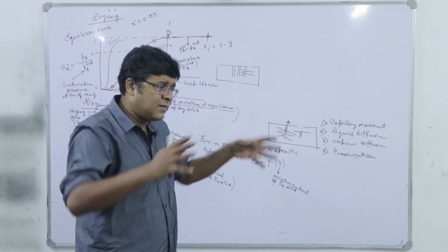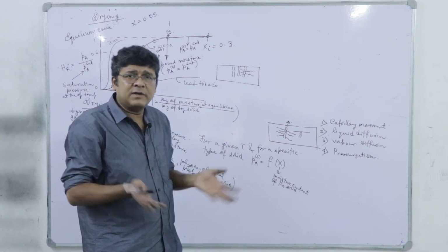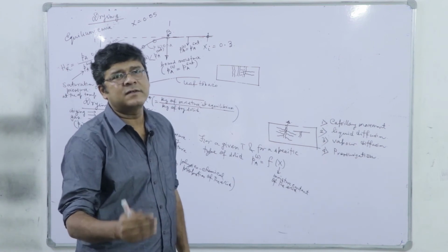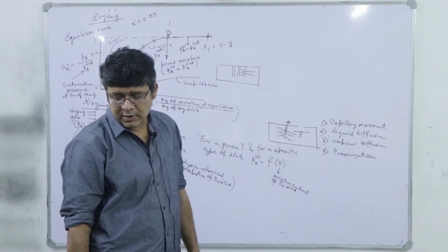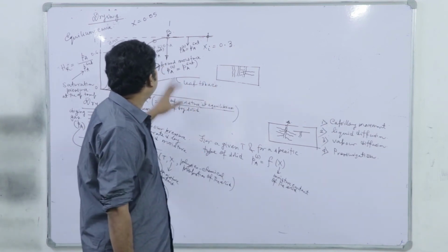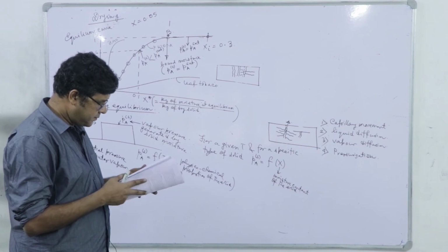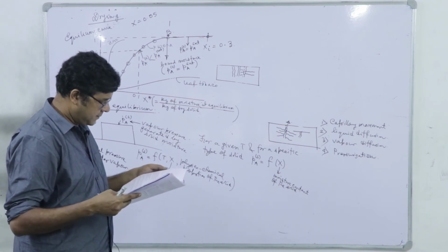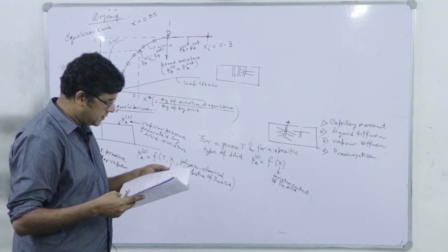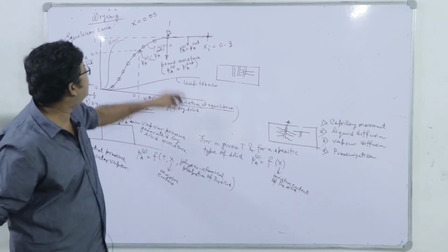So, physically when we have an external film, that is the unbound moisture, and the moisture content that is internal to the wood matrix is the bound moisture, because that moisture has strong physical or physicochemical interactions with these wood fibers, right. So, that is the idea of bound moisture and unbound moisture. So, bound moisture, you see, we can define as the moisture contained by the substance which exerts an equilibrium vapor pressure, that is, a vapor pressure less than that of pure liquid at the same temperature. So, already we have defined it.